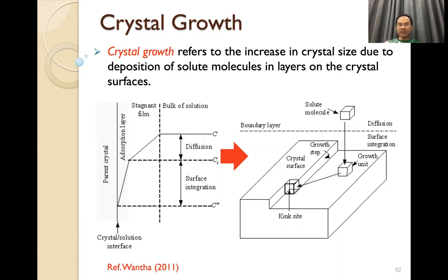For this case, we have two steps. We talk about the mass transfer. We have the crystal in solid form and the solution in liquid form. The solution includes two components, solvent and solute, in the liquid form. If we operate at the supersaturation in the metastable zone, you remember that we have the undersaturated solution that cannot crystallize, and also supersaturation.